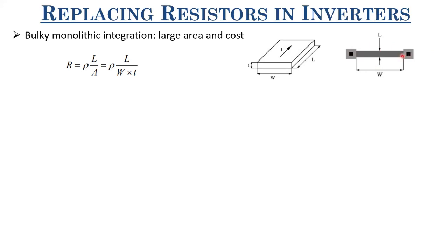And if they want to realize something in between, they can use either doped silicon or undoped silicon. So depending upon what range of resistance we require, we can use metal, polysilicon, doped silicon, or undoped silicon. This is how these resistances look from the top; this is the top view of it. So this is simply the width, this is simply the length, right?